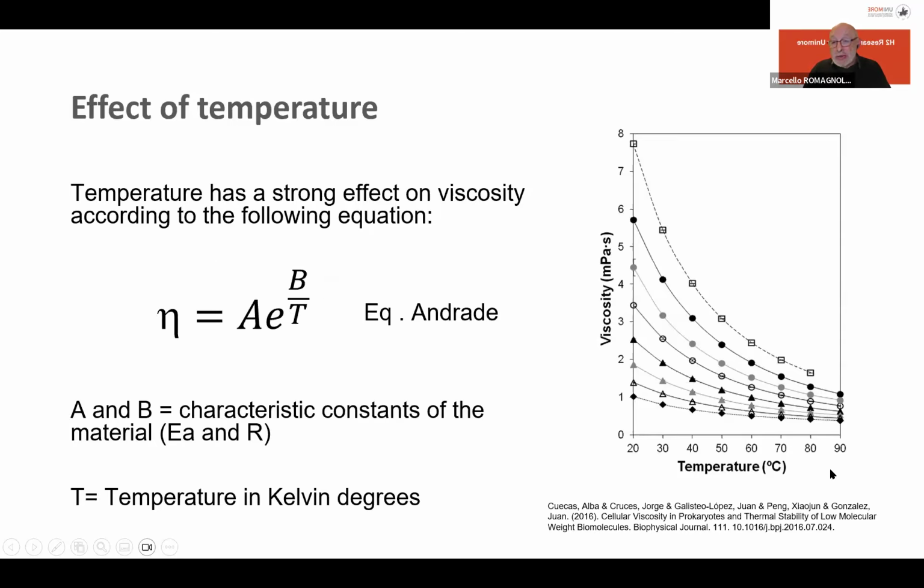So when we increase the temperature, the viscosity of the glaze or the suspension decreases very fast. But if we work at low temperature, close to room temperature, we must consider also that the temperature increases the kinetics, for example, of dissolution of some salts present in the raw materials, but also increases the degradation of the polymer that we eventually have used as additive.